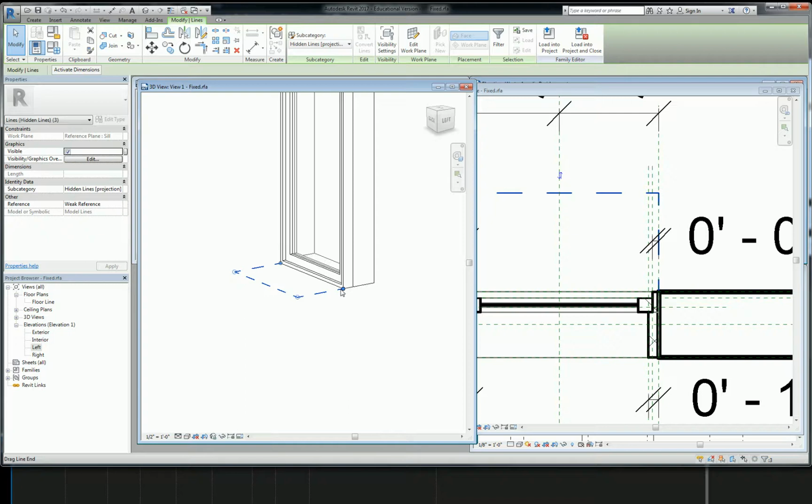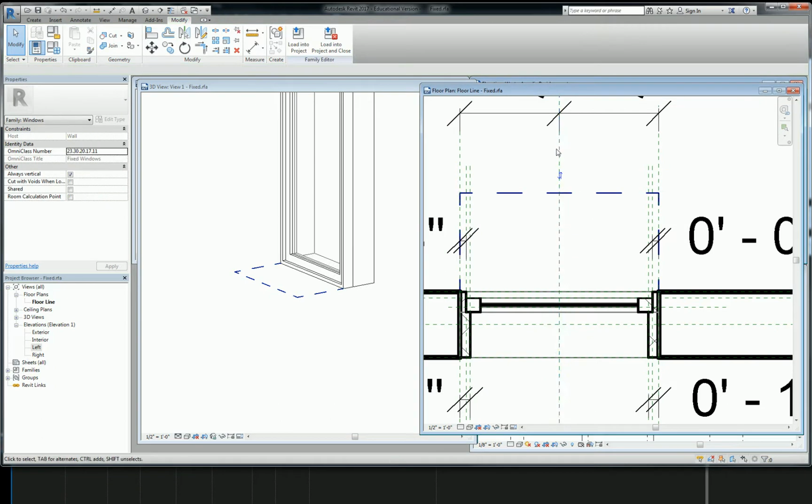Yeah. So if, let's say, you were going to edit a family, but you didn't know if it had any existing work planes, one way would just be to check through the edit work plane feature what planes are available. Yeah. Or just tell by visually looking, so they're green. Okay, so there are a couple of ways to, without changing the way they look, which Revit doesn't really like you to do.